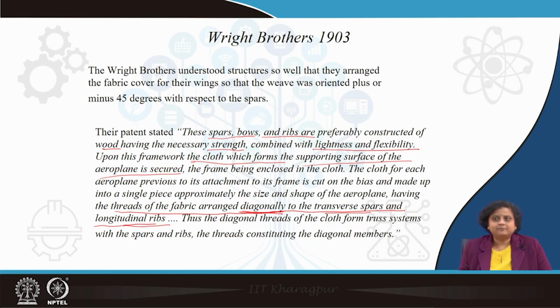So, this is an example that I have put primarily to emphasize how the understanding of basic mechanics, the basic idea that the maximum shear will happen at 45°, helped those engineers and designers earlier also to find an effective design which was successful. It was not rocket science, but a very simple, clear understanding of the mechanics.